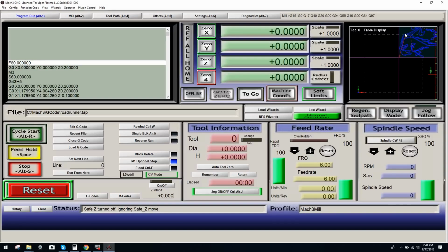And if you are penetrating any of this dotted line anywhere around the perimeter of the table, you will get this message if you decided to go to machine. And believe it or not, I've had many people actually go to do that. So let's just see what happens if I click on it. Soft limit warning, and it's warning you on the X max. Well, it's obvious right now you're over the perimeter of the table, therefore it's warning you. If you click yes, you are going to have a heap of trouble. So naturally you would click no.